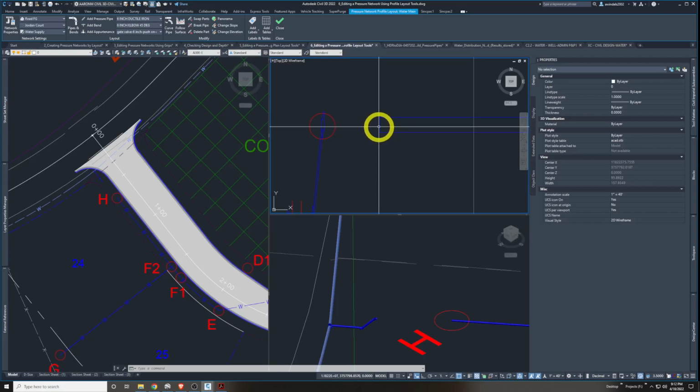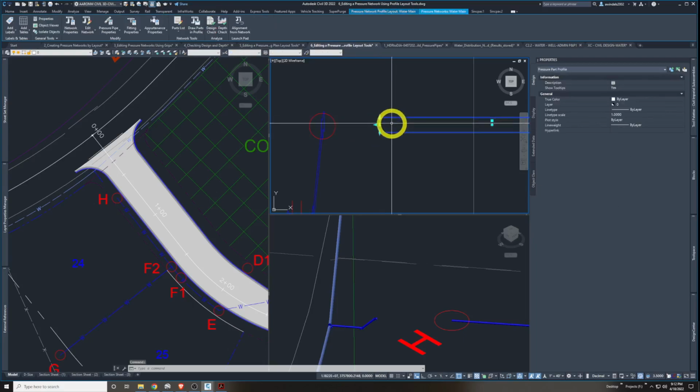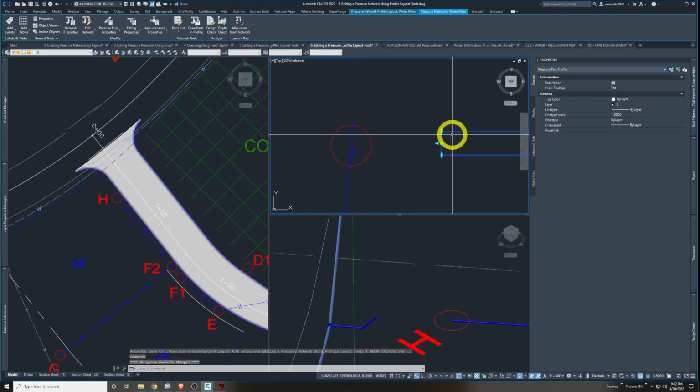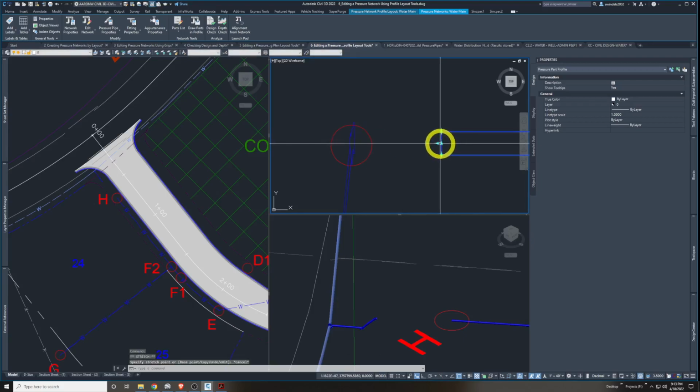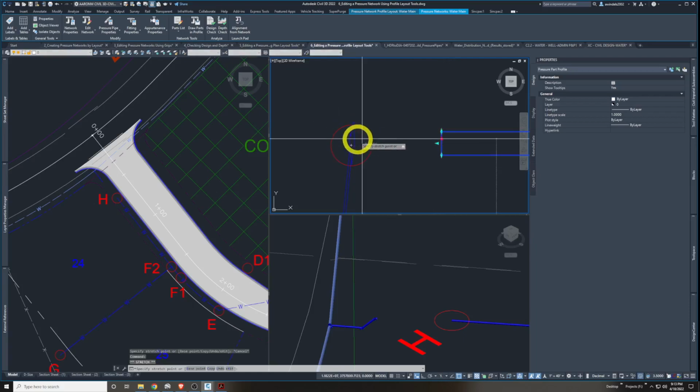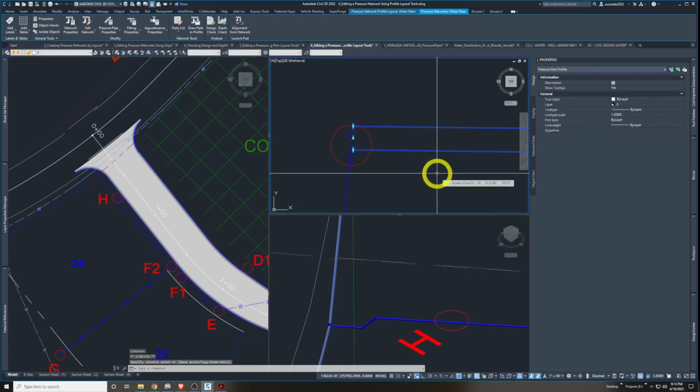So let's click this pipe next to it, and at this point let's click the upright triangle grip at the left end of the pipe. And this one here. So let's try grabbing either this one. The goal is to get that symbol to show, or you can click on this triangular grip and drag it in as well. And they'll both still connect the fitting with the pipe.